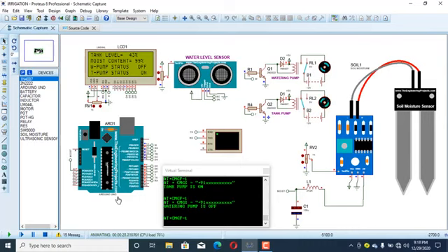And the soil moisture sensor will detect that, and we are going to water the plants. So it would be illogical, because we are going to kill those plants if we water them right at noon, right? So we are going to use the RTC module to operate our system, maybe from 8 a.m. to 9 a.m. and then choose other working hours, maybe from 17:00 to 18:00, right?